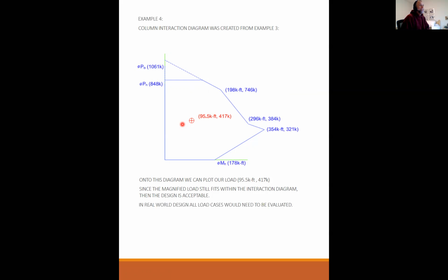At some point, you start needing software just to get your hands around all these things. But principle-wise, this is the principle. Our amplified load is still inside the interaction diagram, so this particular load would still be acceptable.